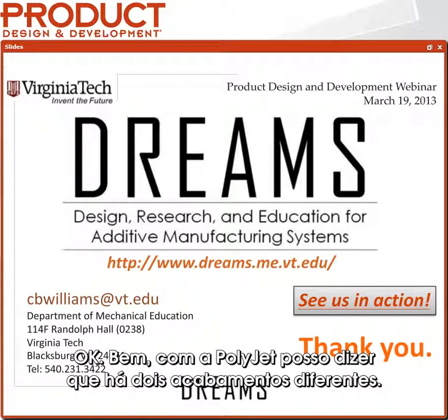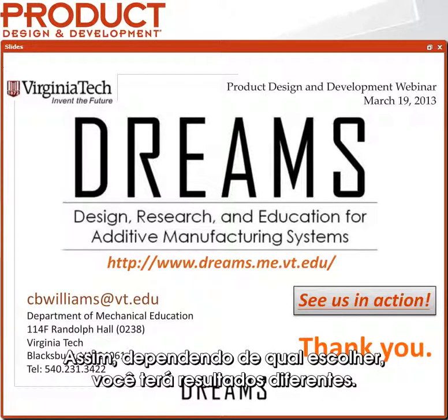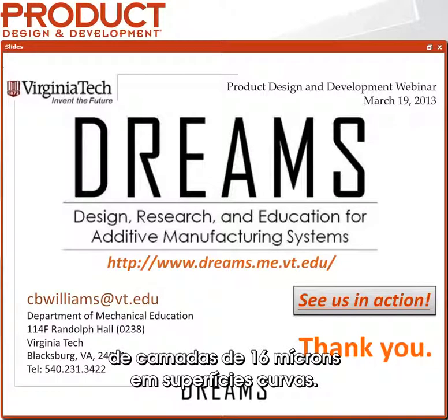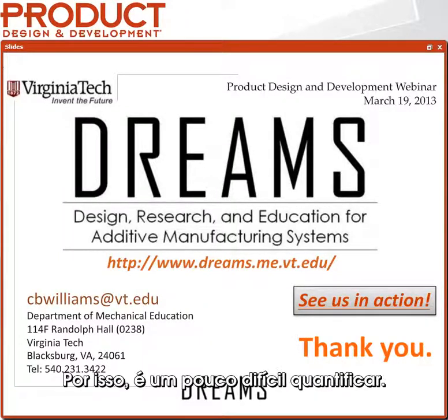Okay. So with PolyJet, I will tell you there's two different finishes. There's a glossy finish and a matte finish. So depending on which one of those you choose, you're going to get a different result. Again, as we referenced before, with a 16 micron layer printing capability, when you're printing a curved surface with the PolyJet technology, you get very, very smooth surfaces. So it's a little tough to quantify.